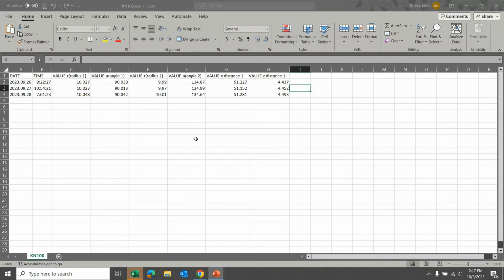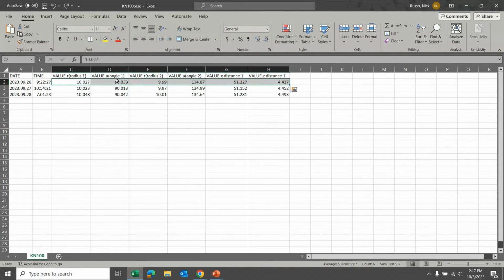So every time you take a measurement, it will input the values into a new row with a timestamp. And you can see how consistent your machining operation is over time. So we can set the file type as to append results instead of replacing the file every time this measurement is performed. So it'll give you a running tally of what your measurement looks like over time.